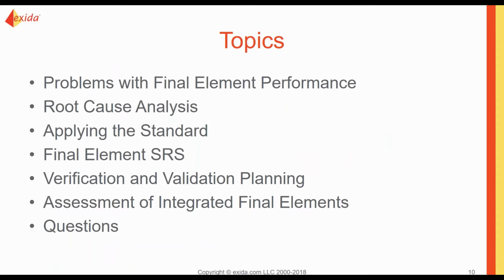So starting today, let's look at what we want to go through. First, I want to review the different problems we've observed with final element performance. Then we'll take a look at what the root causes are, how we apply the standards to try to minimize or eliminate them, what we're calling a final element SRS, what that is and why it is required, verification and validation planning steps for final elements, then talk about what can be done to assess integrated final elements, and at the end, open it up for questions.